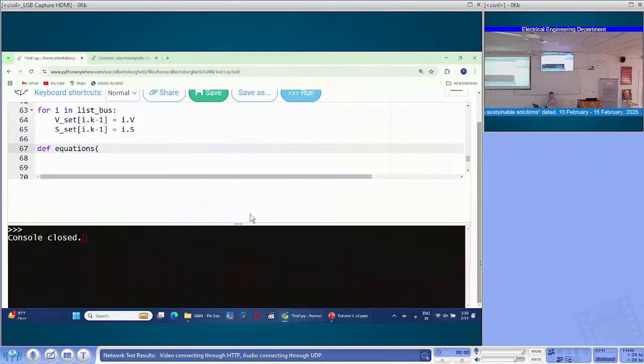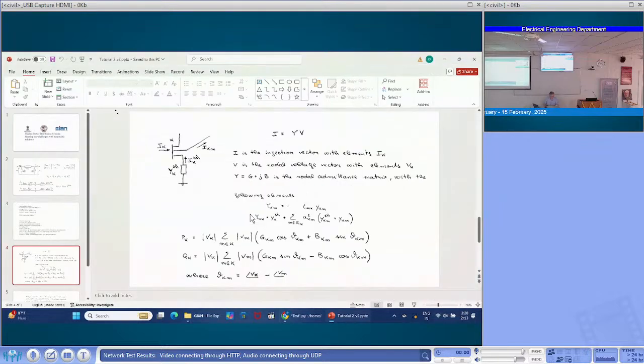And well, what are the equations? Are these two. So these two are the power flow equations. So the power injected, active power and reactive power in bus K, it is equal to the voltage in bus K times the summation for all the buses, the voltage of the bus, Vm, that can be also K. So in our case, it is a single line.